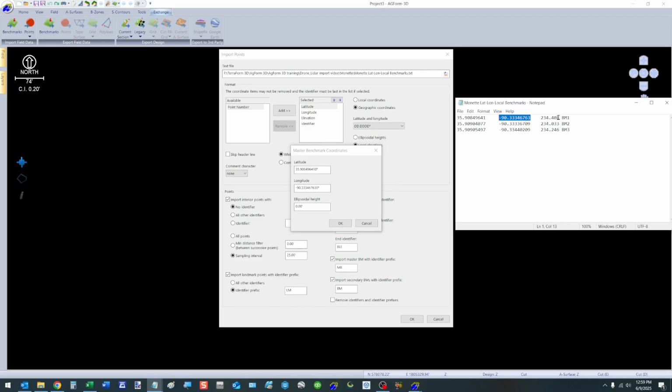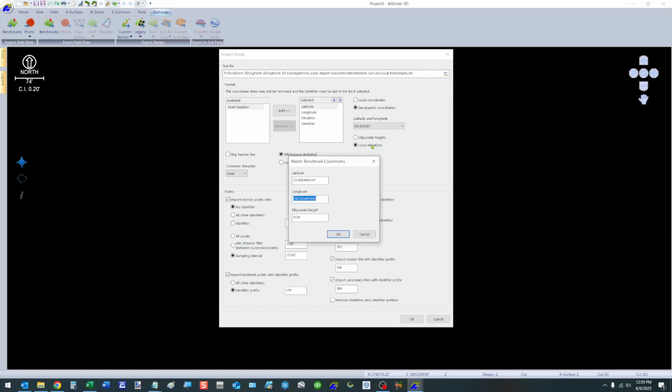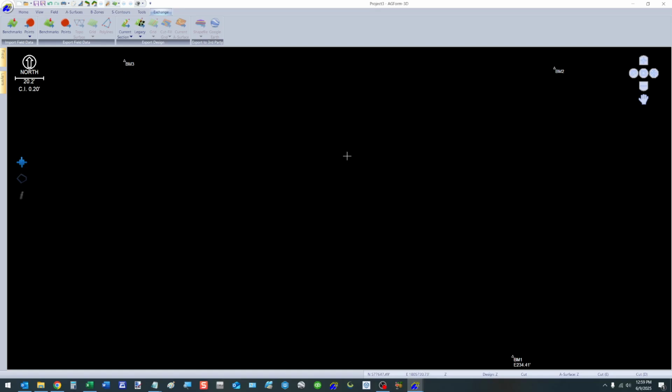You see here we're putting in our local elevation, MSL. But see down here it still says ellipsoid height. Previously, when you chose local elevations, this would say local height. So there's an error in there. So when it does this calculation, even though you punched in local elevation, it's calculating it based on it being an ellipsoid height. Then I'll show you what kind of error you'll see. So we click OK. Same thing here. We got our benchmarks. We go to the field menu, click on List.